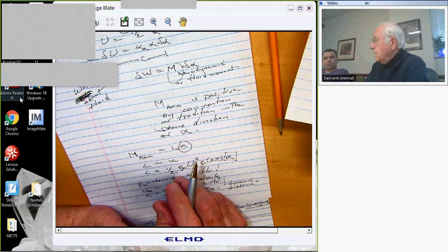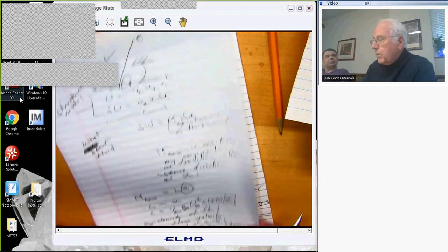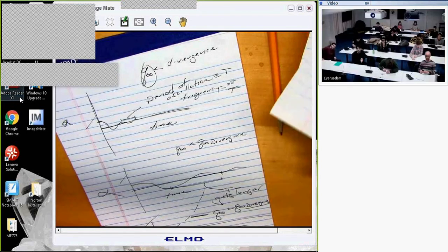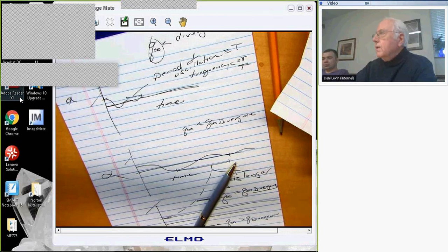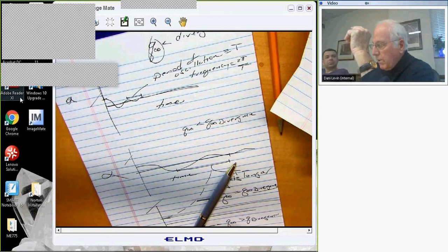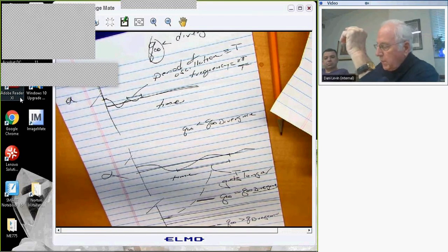The other question I thought you were asking was, all of this is based on a linear model, as the spring moment is proportional to alpha, the aerodynamic moment is proportional to alpha, so everything is proportional to alpha. And within the framework of linear theory, all we can do is predict what happens up to the point where this thing begins to diverge.